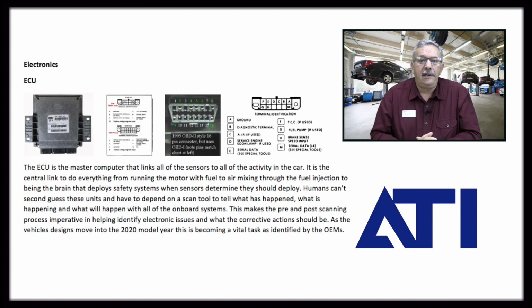I check it through the diagnostic link from 95 through current. We have the OBD2 style connector that you would connect the scanner into, and basically that would read the diagnostics for the vehicle. And as vehicles move into the 2020 model year, this has gone from being a non-essential task to an essential task, as we described earlier, that we go through all these scanning processes.